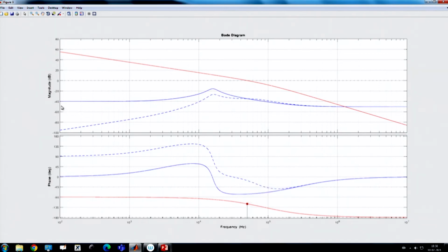But for the open loop output impedance, you see at low frequency it is much higher than the closed loop one, and then there is a peaking, and then at high frequency it will be decided by the ESR that we have discussed. And for output impedance at high frequency, your inductor will behave like an open circuit. So it is an RC circuit, the capacitor will behave like a short circuit, then the RC and R parallel combination will give you the output impedance at very high frequency. And for open loop low frequency, it is RL and R that will come in parallel, that we have discussed.